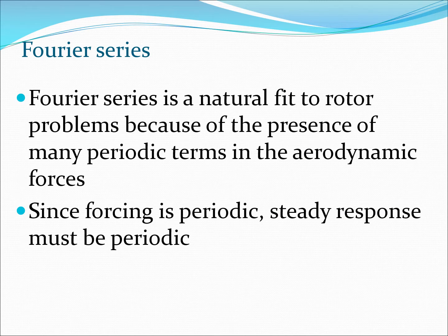Now we know that here we have a system which is periodic, and the presence of periodic terms takes place in the forcing, primarily in forward flight. And therefore, Fourier series would be a natural fit to rotor problems, because whenever you have periodicity, Fourier series is a very good way to solve such problems, because periodic functions can be represented very well in terms of Fourier series. So since the forcing is periodic, the steady response must also be periodic.